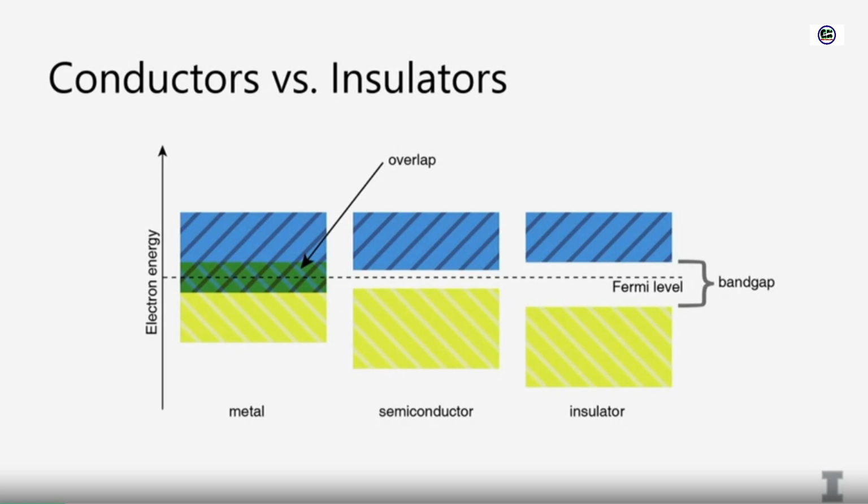Often these different levels of energy can be separated. There's a certain amount of electron energy you can put into the material that can get electrons in there, and that's called the valence band. That's a band of energies where you can get electrons into the material. There's also another band called the conduction band, which is where electrons actually move.